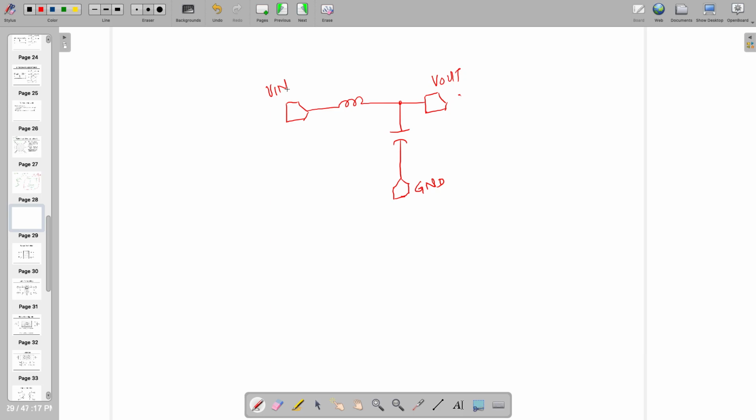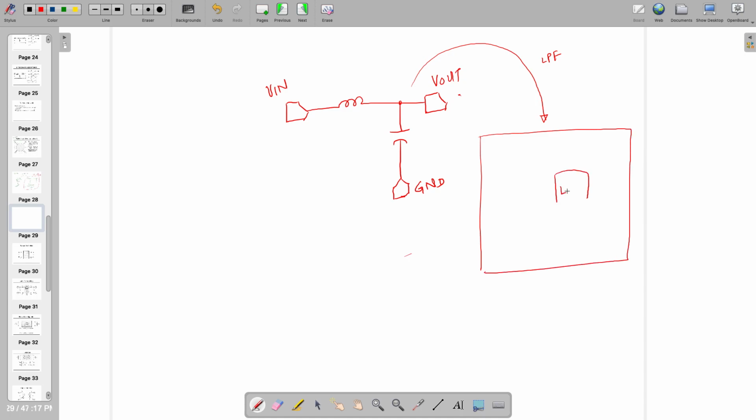I want to simulate this, then I'm going to make one layer higher than this one, where I'm going to call this circuit. If this circuit name is LPF, then in that particular test setup, I'm going to call the low pass filter. There will be three things already available, where they are going to ask, here please connect ground, so I'm going to connect ground.